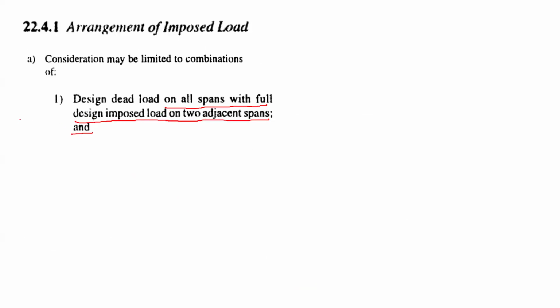This condition is for maximum support moment. Whenever we have two adjacent spans with total load and then alternately only dead load, that condition gives maximum support moment.